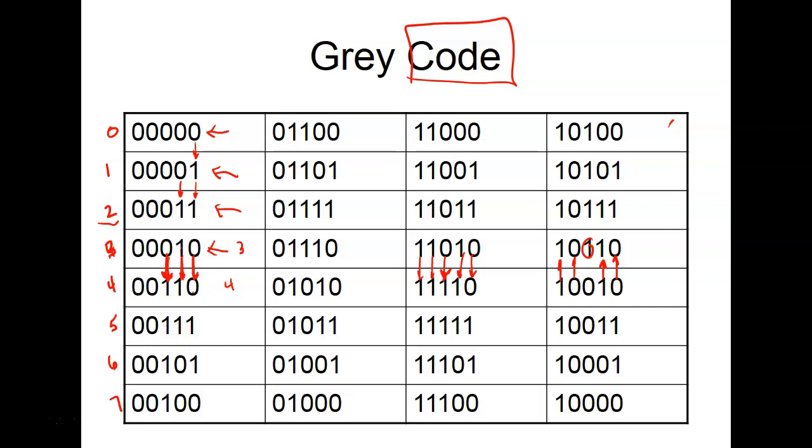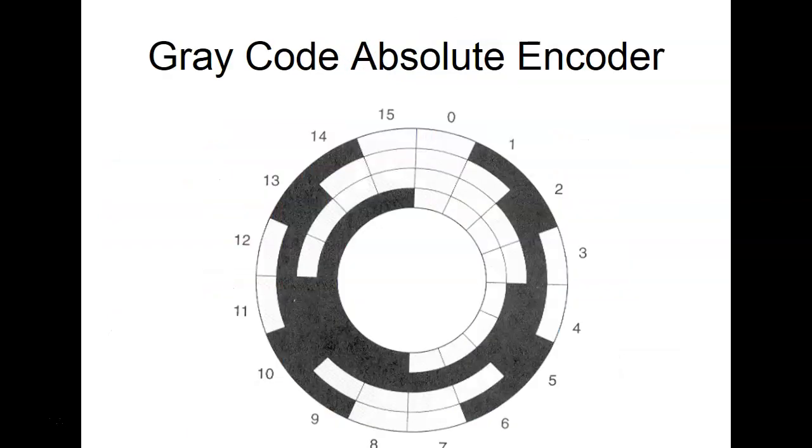Yeah, you could Google it. You can search gray code to binary, and it would come up. There's a place where you can enter your gray code on one side, and it does the conversion for you. So this is a gray code absolute encoder right here. So you can't actually use the binary anymore, right? You understand that because it's code. So you're going to know that, guys.